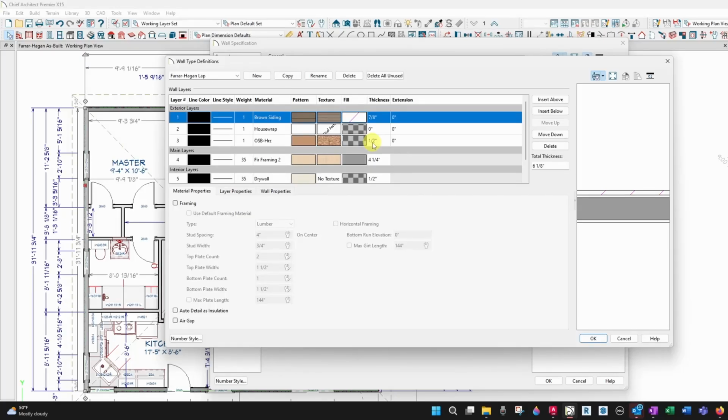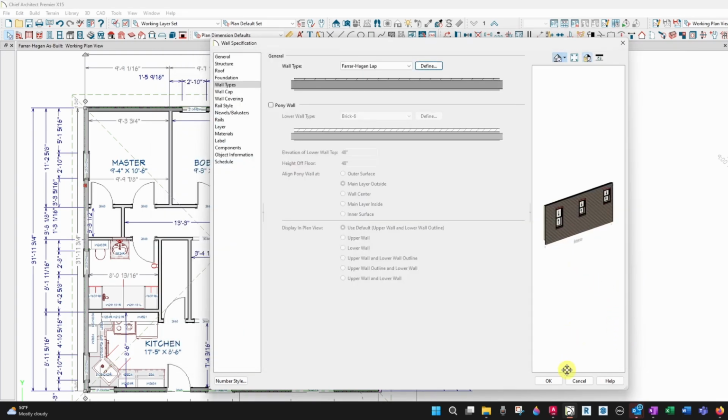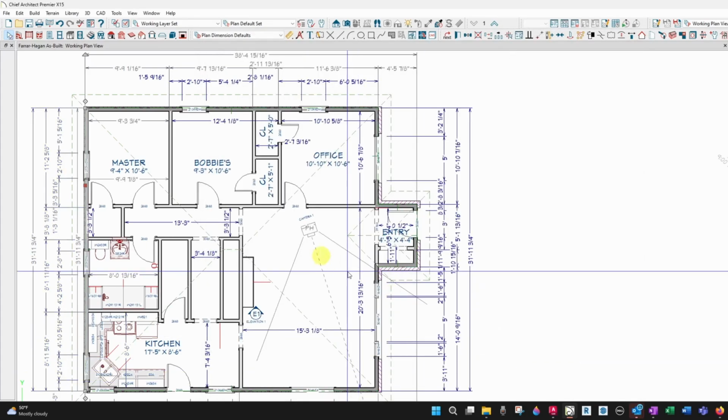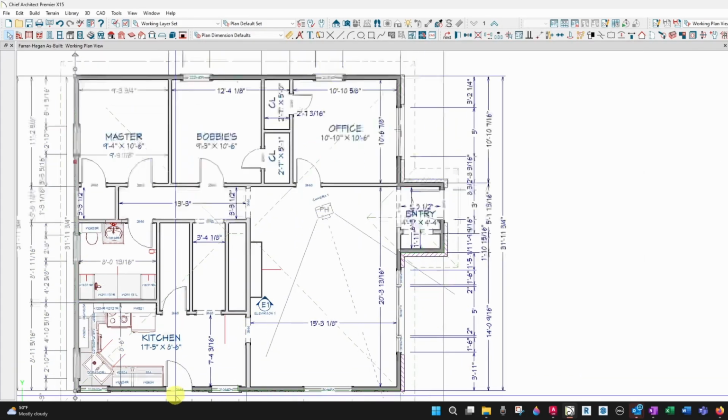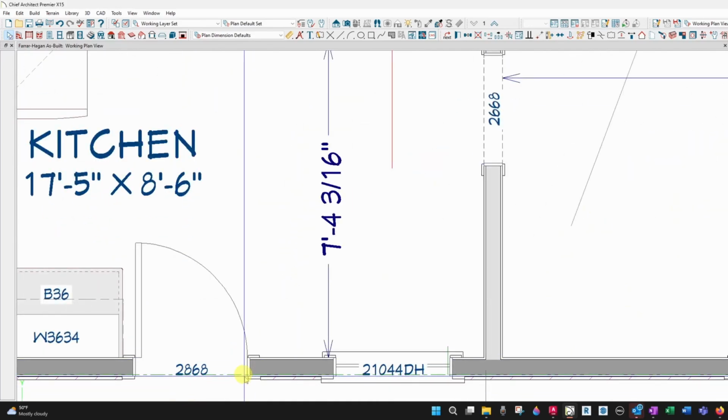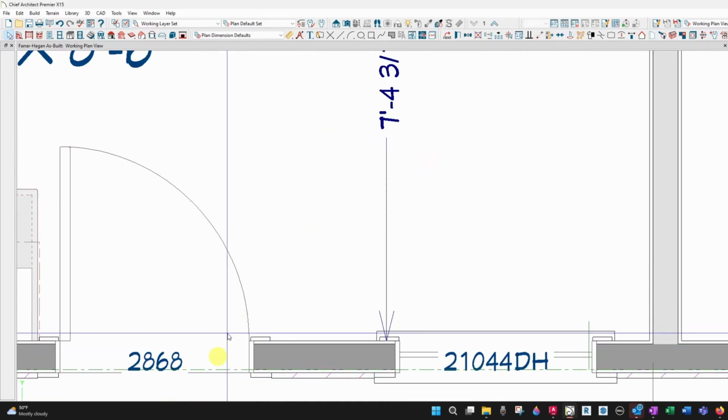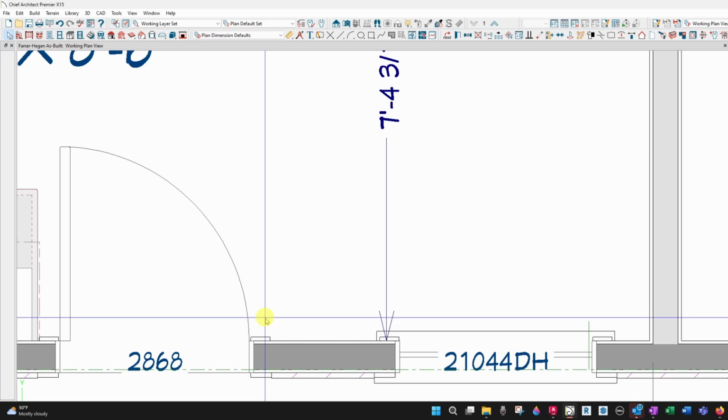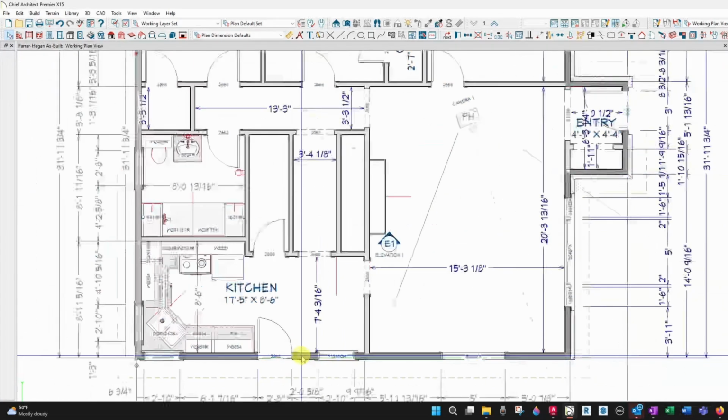Inch was for OSB or whatever sheeting is out there. I haven't got to that point yet. Then 4 1/4 and then half for the drywall on the interior. And I got this information from one location. And so I don't know if it's consistent. So we're going to have to probably do some determination. But when I open this door, on this jamb here is where I measured my wall information for this location.